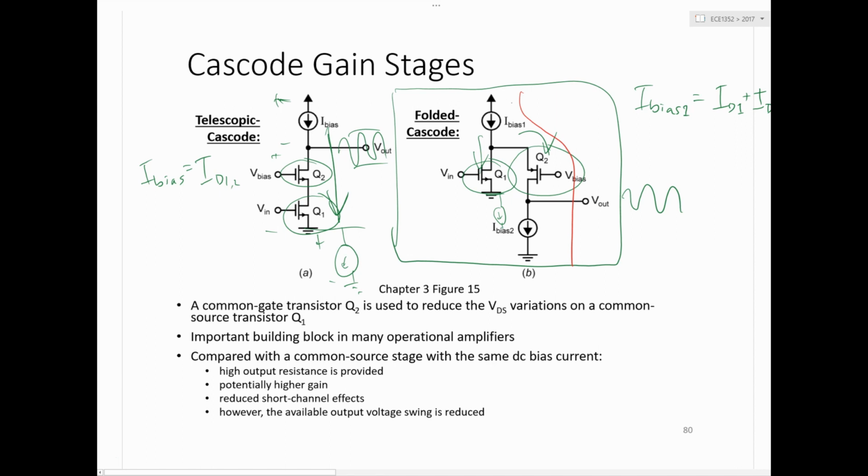Whereas on the left, I suggested that you'd probably want two transistors stacked for I bias in a cascode, here you've really already got one of those PMOS transistors there. So you only need one PMOS transistor up here. And looking up from the output, you'll still see two, kind of a cascode. So you basically save one transistor in the stack.